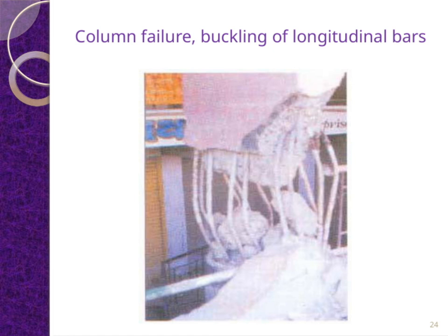Buckling happens when the compressive stress in these bars exceeds a certain critical value, causing them to bend or deform laterally. This deformation weakens the overall load-carrying capacity of the column. It's important to recognize that the failure might not always be due to crushing of concrete, but can also result from this buckling of the reinforcement. Understanding this failure mode helps us design more resilient columns.